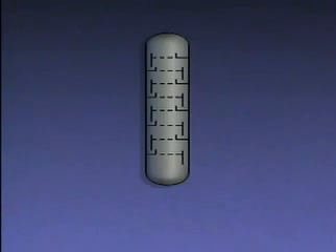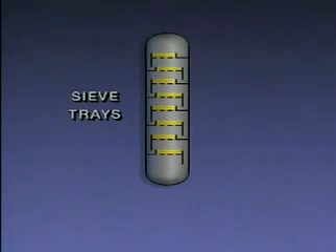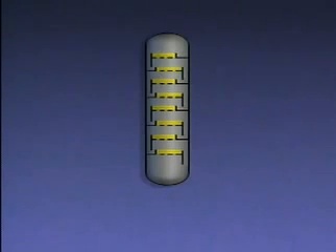At the heart of a distillation system is the distillation tower. Basically, a distillation tower is a series of distillation processes, or stills, stacked on top of each other. The process of distillation is sometimes referred to as fractional distillation or fractionation, and distillation towers are sometimes called fractionators. Fractionation is distillation that occurs at different levels in a tower. This is a simplified illustration of the inside of one type of distillation tower. This tower uses trays called sieve trays to separate vapors and liquid. The trays are spaced throughout the tower. They're called sieve trays because they have many openings in them, like a sieve.